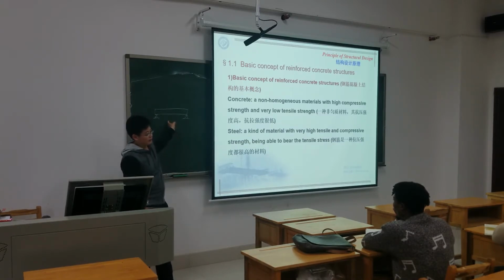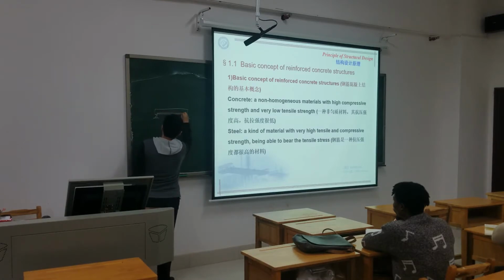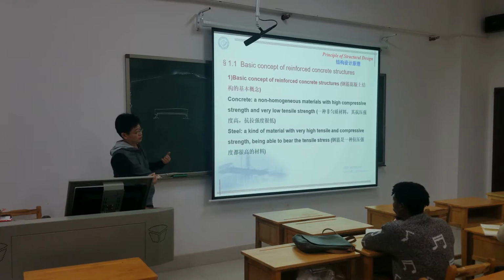Inside the beam, upper or lower? Down. Yes, normally the main steel is put at the bottom to resist the tensile force. The upper part is just concrete, sometimes.